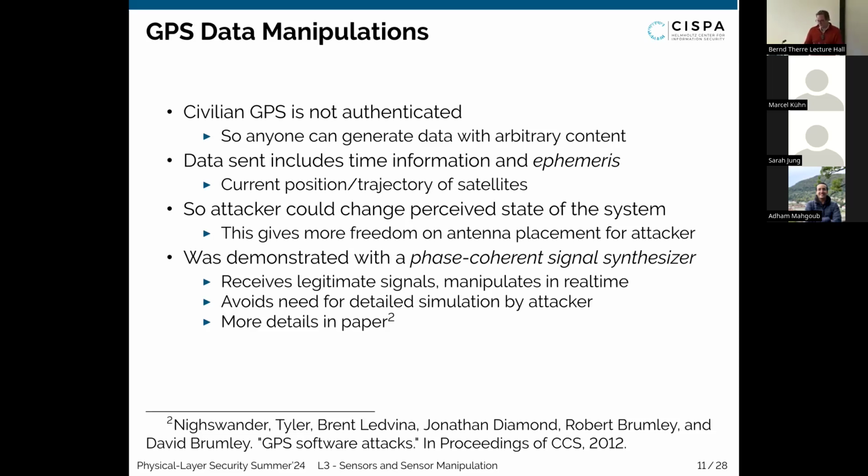So the victim has a known location. And then if we want to transport the victim to some other location, we could start a very brute force GPS spoofing, kind of hammer down the legitimate signals, and send signals for a completely different location. Then, within the GPS receiver of the victim, or if the victim is monitoring its own location, it would immediately see that it's jumping 1 kilometer in a second or something like this, and it could notice this and notice an attack.